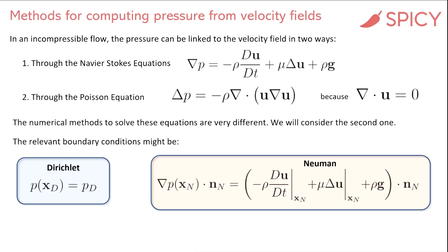When this is a wall, what is typically done in CFD is to set this quantity equal to 0, because if in this wall we have the development of a boundary layer, we know that in boundary layers usually the pressure gradient along the normal direction, normal with respect to the flow, is equal to 0.